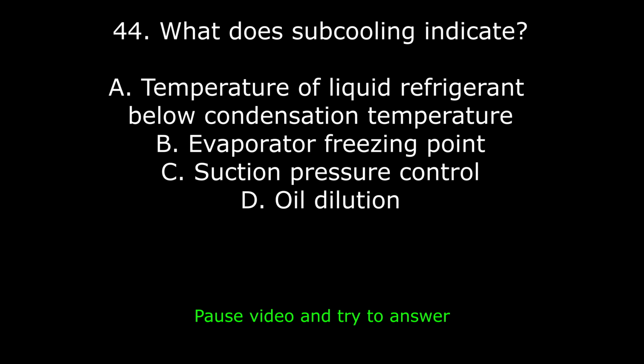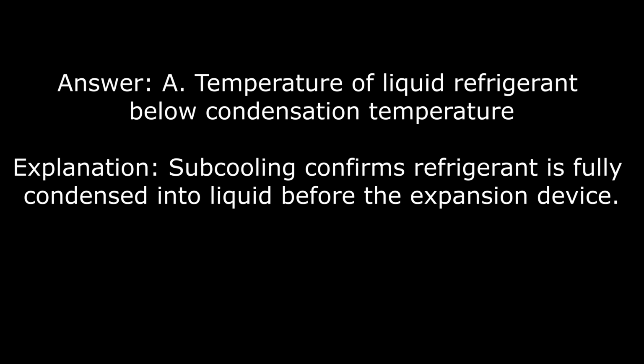44. What does subcooling indicate? A. Temperature of liquid refrigerant below condensation temperature. B. Evaporator freezing point. C. Suction pressure control. D. Oil dilution. Answer. A. Temperature of liquid refrigerant below condensation temperature. Explanation. Subcooling confirms refrigerant is fully condensed into liquid before the expansion device.